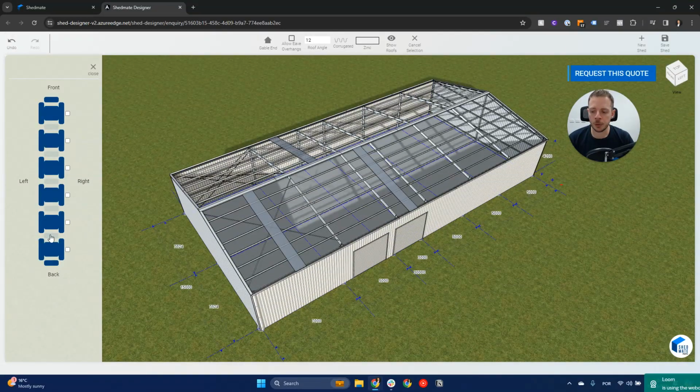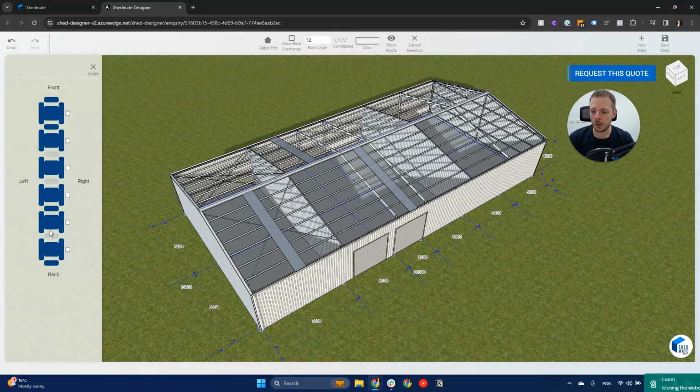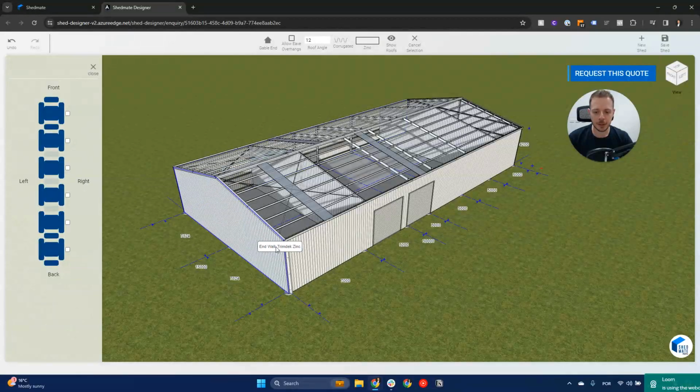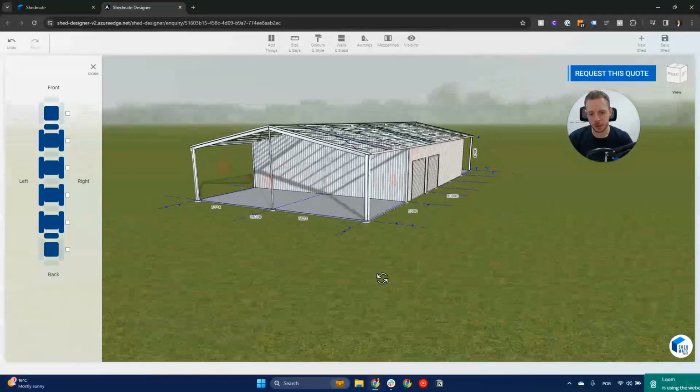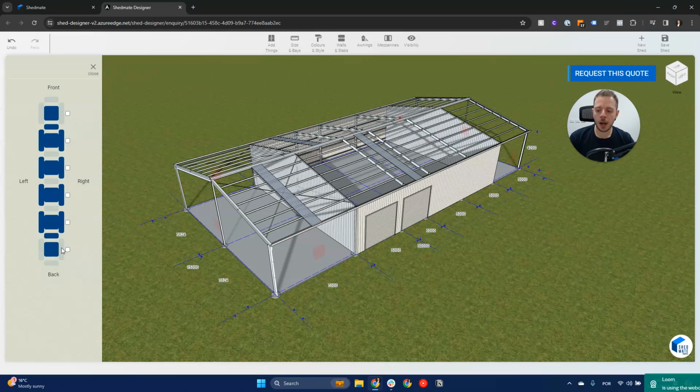So from here, you could click on the middle lines, and these are internal walls. I can add and remove them as I want. For instance, just adding 2 here, or I'm just going to move to this end wall. So we have 2 internal walls. And if I want, I could delete the walls around by just clicking on the back and front. So now I have a structure that looks like a kind of carport, right? But much larger.